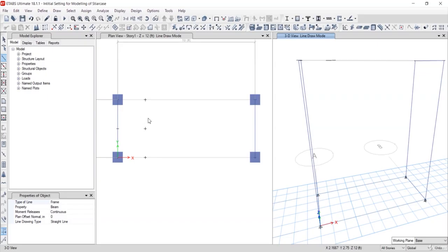Okay, so for that I will simply go to this option here. Okay, draw floor slash walls, and after that I will select the staircase slab, and from here I just simply need to join these points. Okay, and then right click. Okay, you can see as I have closed the loop, it has drawn that slab.